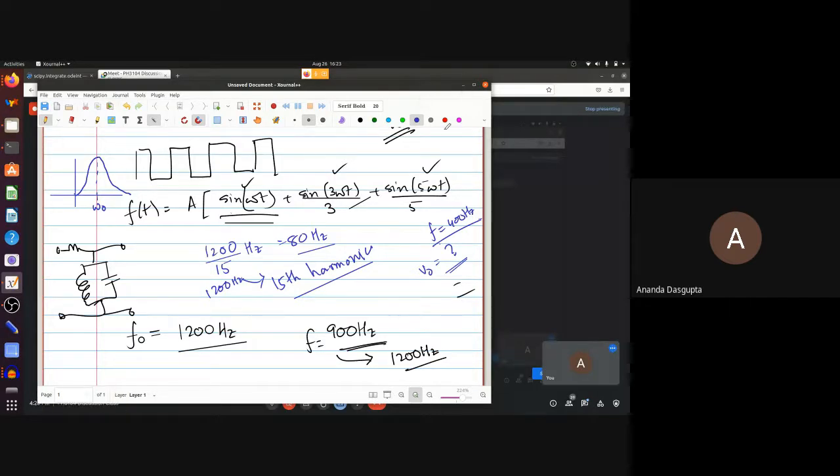Come on. The 400 Hertz input has a 400 Hertz term, there's a 1200 Hertz term, it also has a 2000 Hertz term, and also higher frequency terms. Now, why did we expect there to be a peak? Because the 1200 Hertz term in the input is close to resonance, right? So this one which is far away from resonance and this one which is far away from resonance will be suppressed quite a lot. So you will effectively see only this output, which is why we said the output peak will be only 1/3 as high as the original peak that you saw.